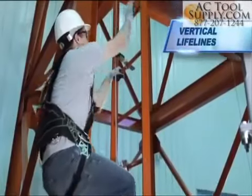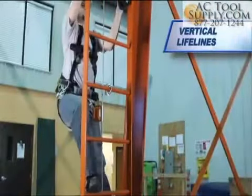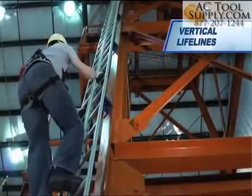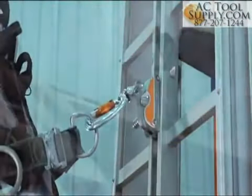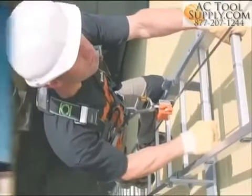Vertical lifelines are connecting devices available as rope or cable and used in conjunction with rope or cable grabs. These grabs are designed for hands-free operation, easily sliding up or down a lifeline as the worker moves, but instantly locking in place in the event of a fall. Common applications include roofing, window washing, and fixed ladder climbing.